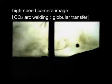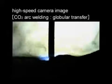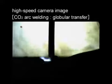Next, we will explain globular transfer mode. In the globular transfer mode, a melted metal particle is formed at the end of the wire. The melted metal particle is then transferred to the base metal when the size of the metal particle at the end of the wire grows large and falls off due to its own weight, and this process generates spatter.